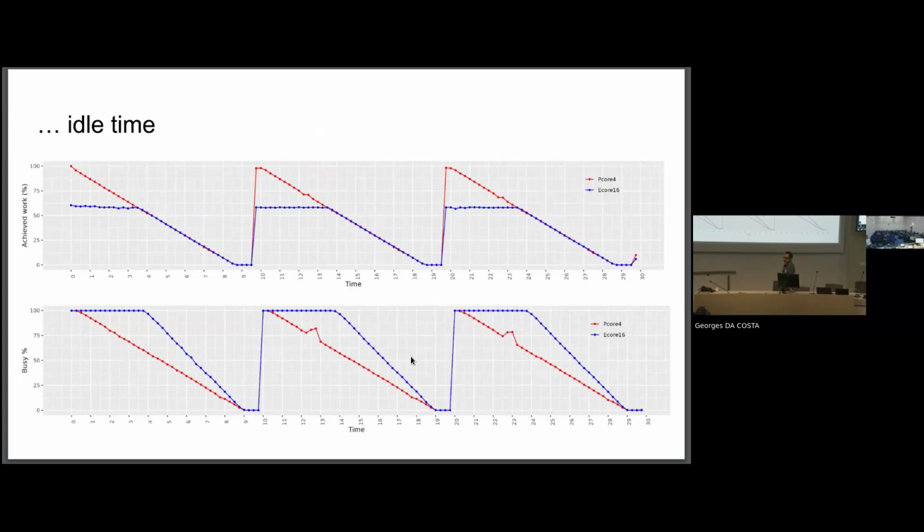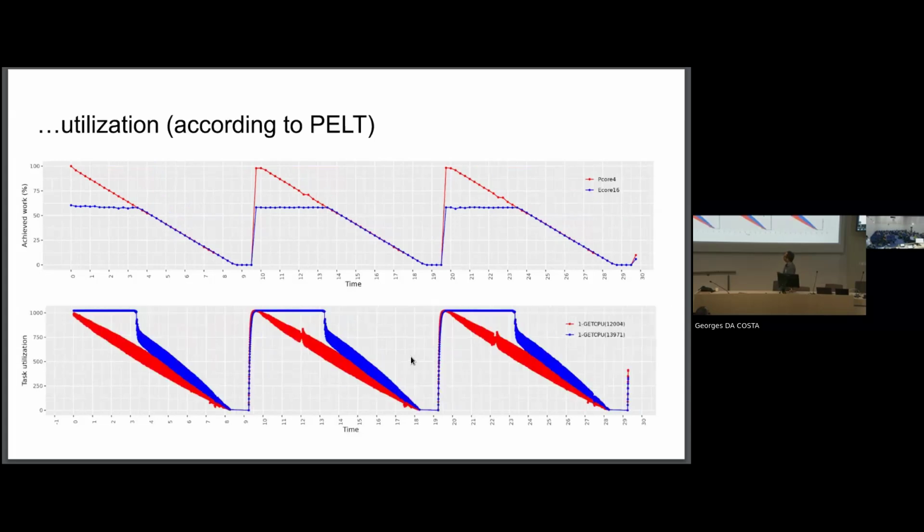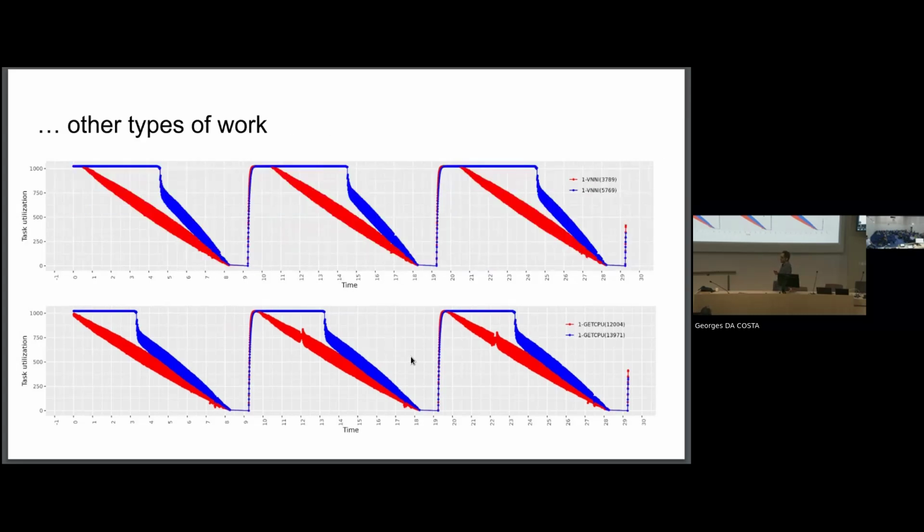And in your next slide, you are using the same... You're considering that you have the same IPC for both cores? Well, this includes the current frequency invariance code. Okay, but only the frequency, not the fact that you're maybe not using the same microarchitecture. Yeah, just the frequency, and actually it is off. I think that Ricardo is going to talk about it. In this next section, I will discuss how that looks when we use asymmetric CPU capacity.